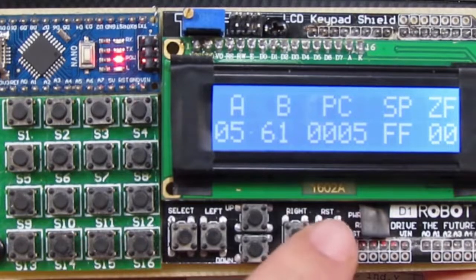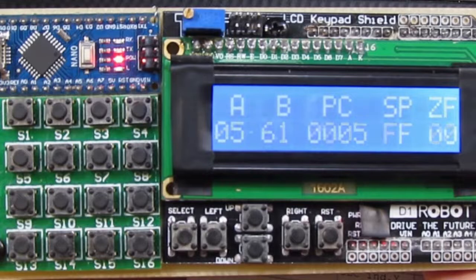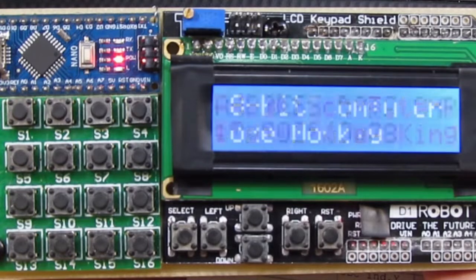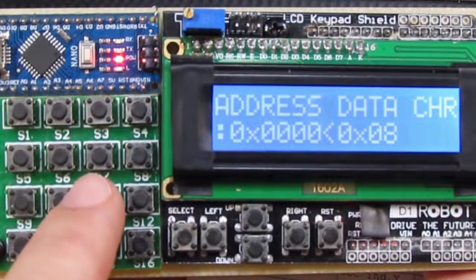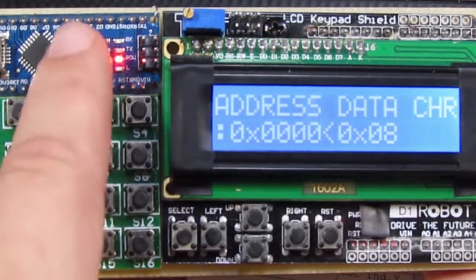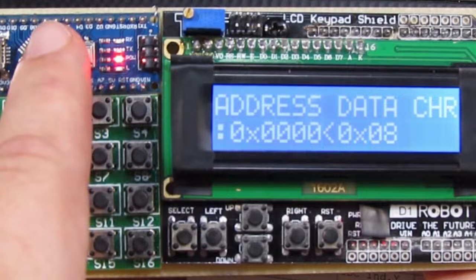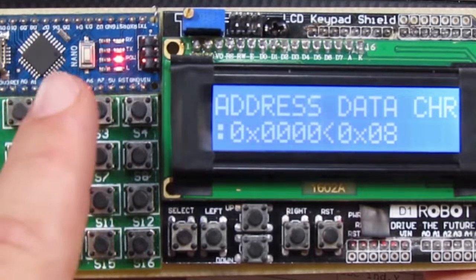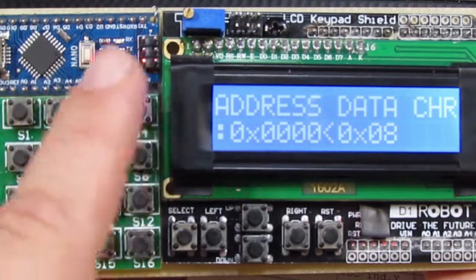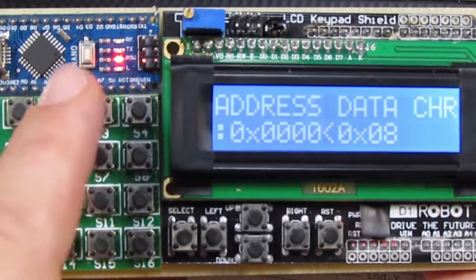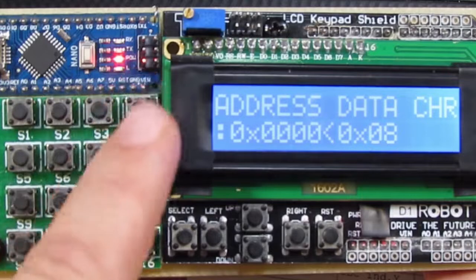Now we'll demonstrate another couple of things. First, let's reset this. We can use up to 1K of EEPROM, because the Arduino Nano has 1K of EEPROM. Actually, this particular board can write even more. I'm not quite sure why. It seems that instead of writing to EEPROM, it writes to its internal flash where the sketch has been flashed. But anyway, I'm just using 1K here.